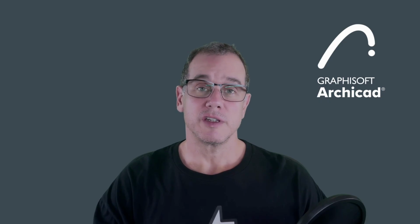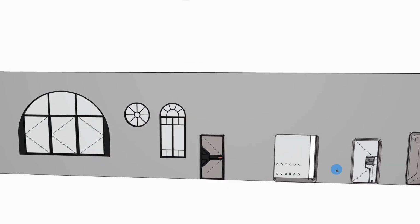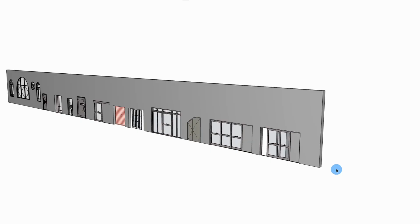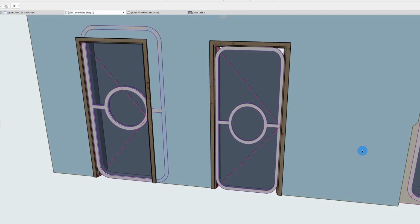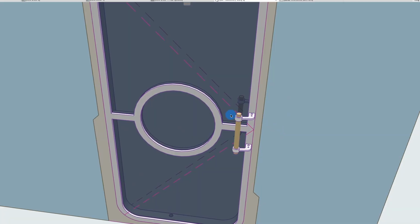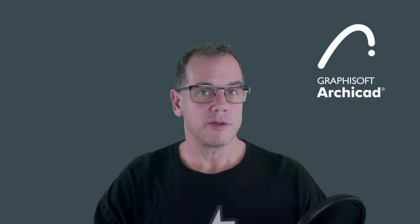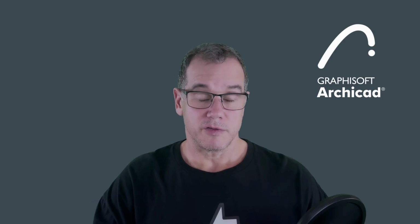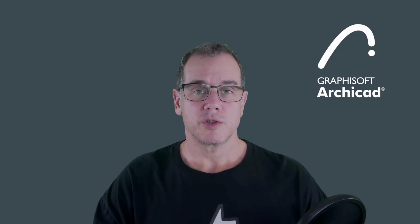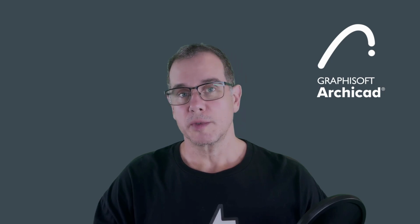Now, in the previous videos, I've covered door examples that I've done in the past, along with how to create doors, custom leaves, and custom door handles using either the create from floor plan or the save as method, where you model what you need and essentially save it as fixed geometry. You can also use the library part maker if you've got the correct subscription.